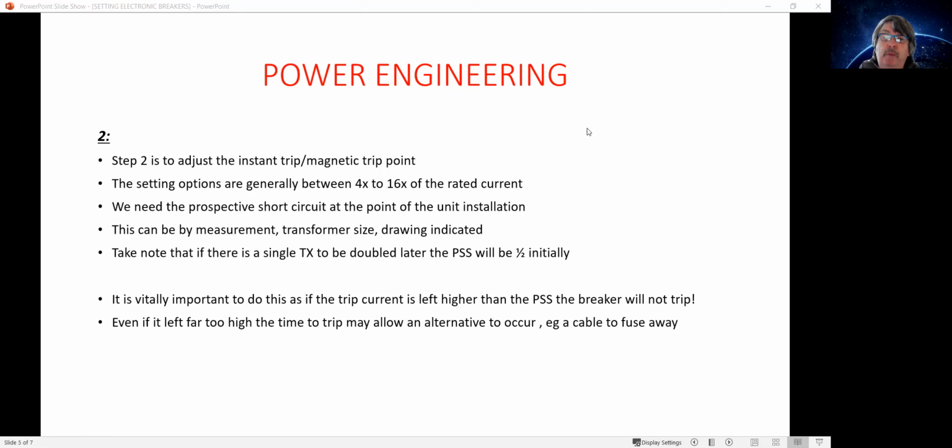And the transformers may not have the capacity to even trip with the intended short circuit level, which is a fatal thing for a circuit breaker, because the circuit breaker will now be put through a huge long-term short circuit at maximum stress before it trips, rather than coming out quickly with a quicker type of trip.